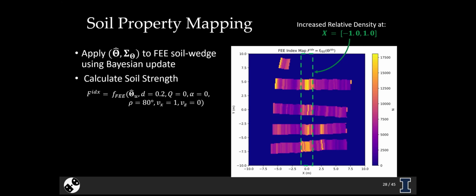There's some discrepancies at the beginning of cuts. That's a known issue, and in particular, this is because we're getting accelerations at this point, and so the actual uncertainties in those regions are higher as well. And then there's a little bit of discrepancies after we come out of this region, and this is really the hard region, and that's a kind of poor controller tuning in reality that results in some more accelerations and jittering that can cause some errors in estimation.